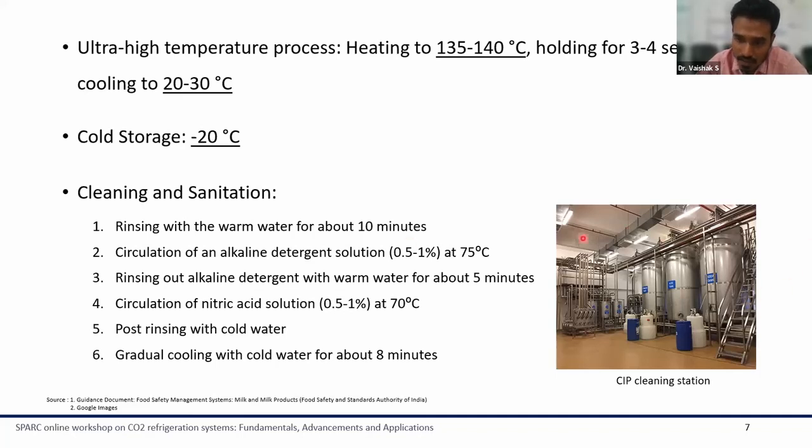And on the right side, you can see the storage tanks for storing these solutions. These solutions are pumped or sprayed to all the components which come in the production line. Generally, in the case of the dairy industry, for the cleaning process, we don't detach any of the pipelines or other components. All the components are kept connected, so it is clean in place.